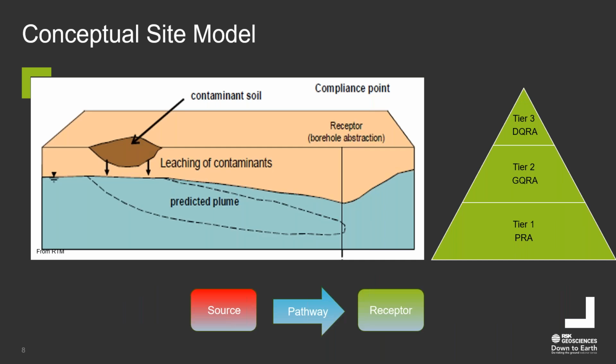A series of investigations in different phases will be required to understand the problem, and then collect data on geology, hydrogeology, and contaminant distribution to develop an appropriate conceptual site model to determine the complete contaminant linkages, which require remediation at the site.